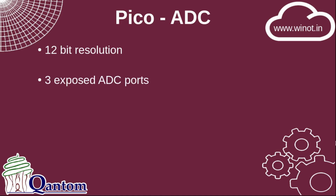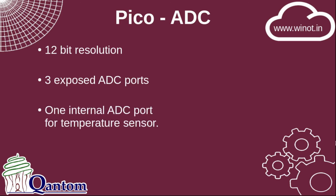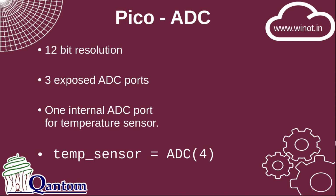The last ADC can be accessed by passing the parameter 4 to the ADC class. So we could say temp sensor equals ADC bracket 4. We can read this value and convert it to a temperature by using the information given in the Raspberry Pi Pico's datasheet. So that's it. Let's move on to another topic.